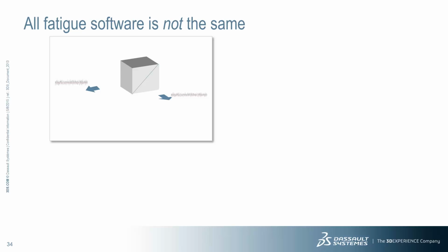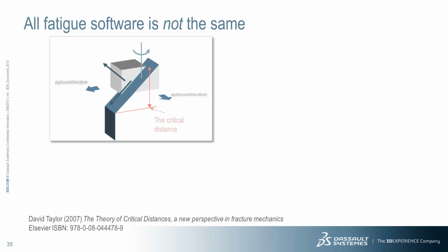We consider the initiation of the crack. For most metals, cracks initiate on shear planes, resulting from a combination of shear and normal strains. For complex loading, FESafe may have to search around to find the orientation of the crack plane, and this is called critical plane searching. The damage mechanism includes plastic strain, and so FESafe automatically uses a cyclic plasticity model when working from elastic FEA.